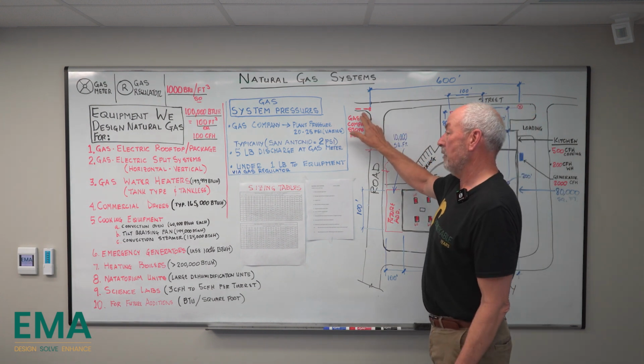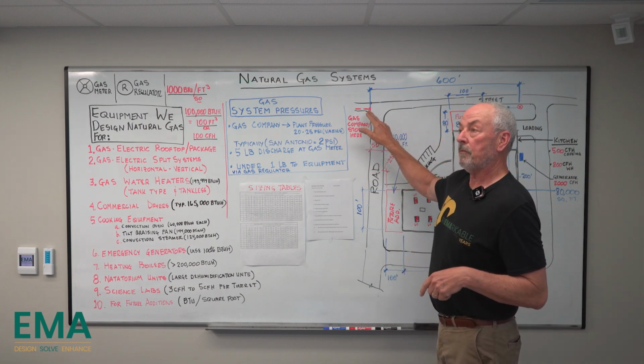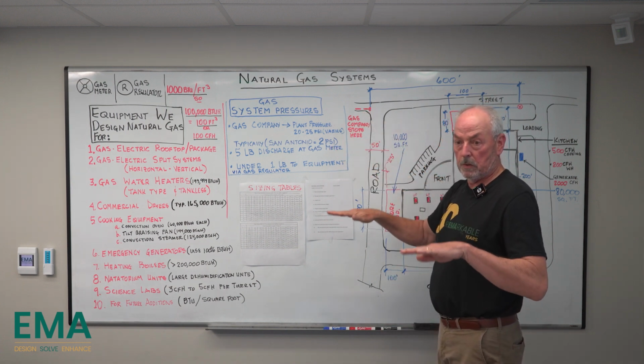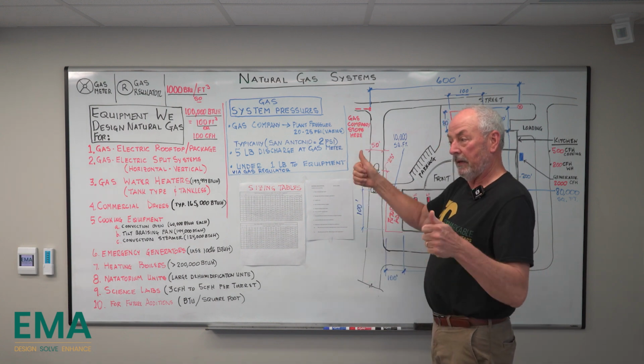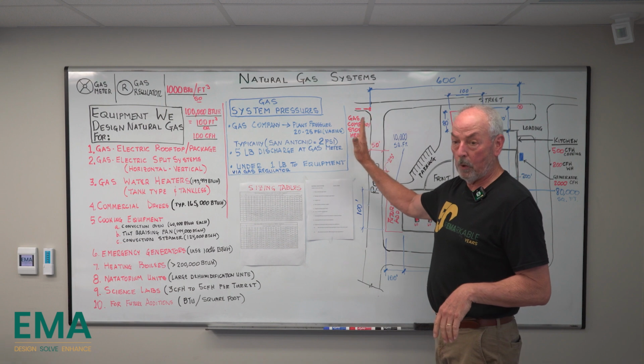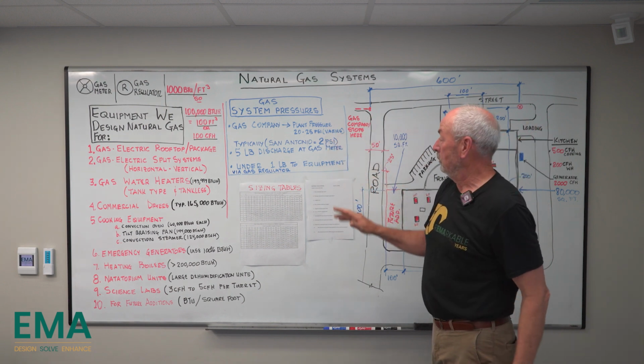The more you have coming off the grid, or if they're off their piping, it affects what pressure is still available, because as your demand goes up, then your pressure drops and they have to boost it. Same thing for domestic cold water systems out in the road.